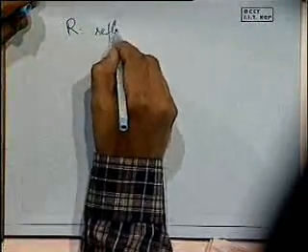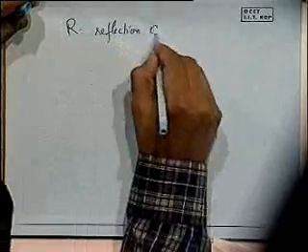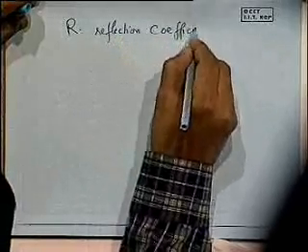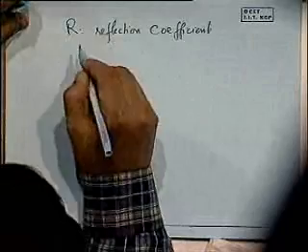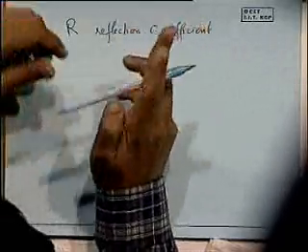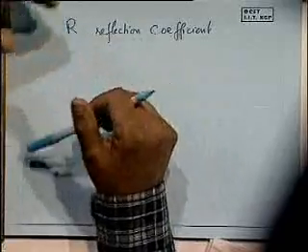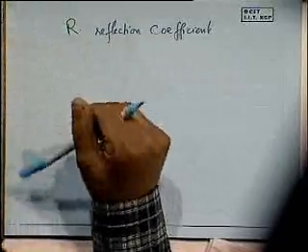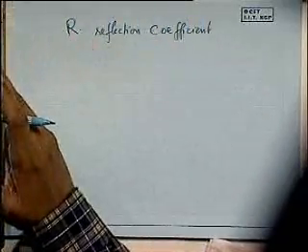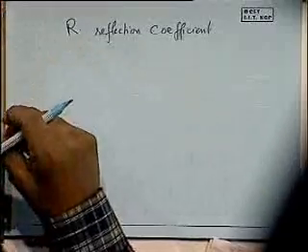It's like a wave if you treat it. This reflection coefficient is the probability that it will get reflected. If the reflection coefficient is large, namely for very large barriers, barriers tending to infinity, the probability that the wave will be reflected back is higher. So we modify the Richardson-Dushman equation suitably to take into account this idea.